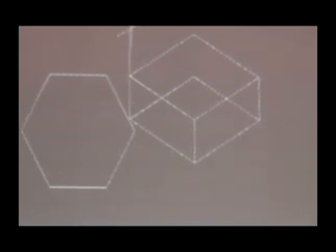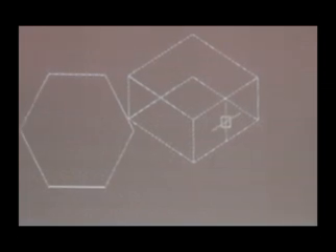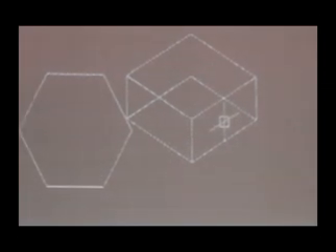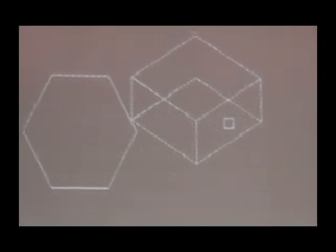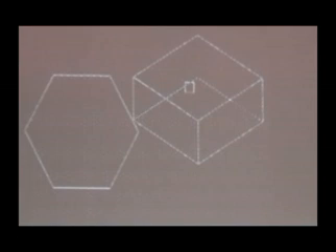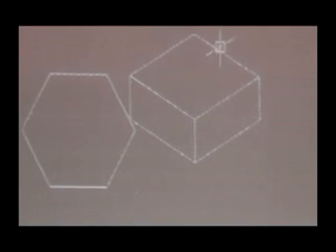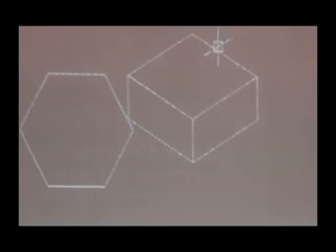Just like this. To show your isometric, you don't show the hidden lines. Whichever portion you want to remove, I can erase it, so you can go for the erase command. I can erase this. So this is your isometric. It's easier to draw the isometric views here.